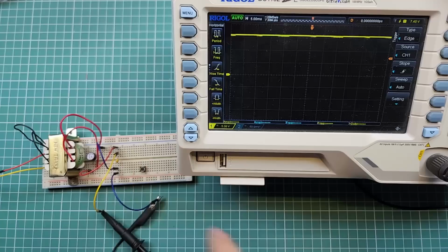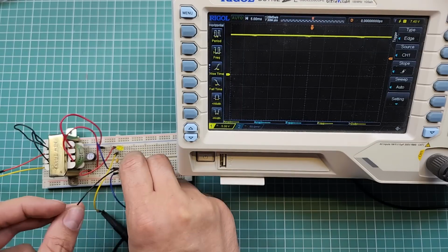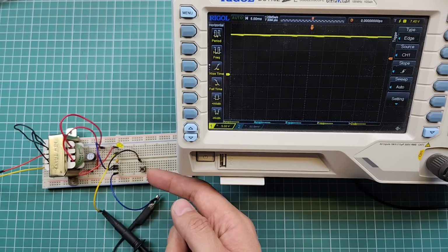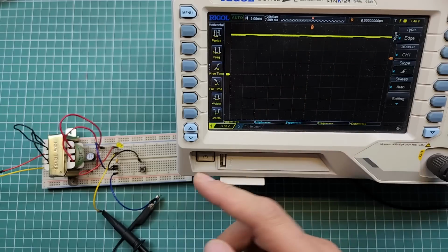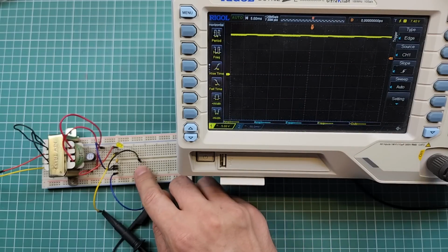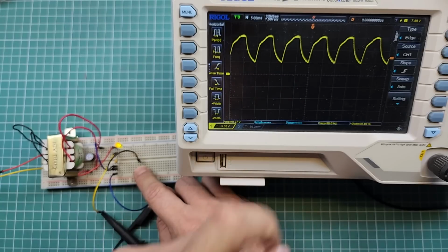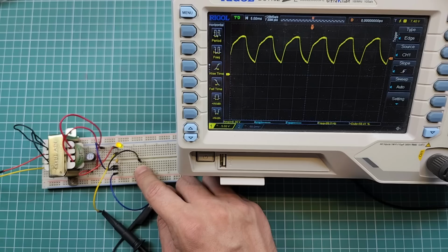This is somehow normal. The higher the current you draw, the bigger the ripples will be. However, a 10 microfarad capacitor is very low in fact. Now I'm gonna add an LED with a push button to see how it impacts the output. When the LED is off, the output is clear and smooth, but when I press the button, the ripples come back. There is a 10 volts peak-to-peak ripple in a 16 volts output. This is horrible. To reduce the ripples, we need a capacitor with a higher capacitance.